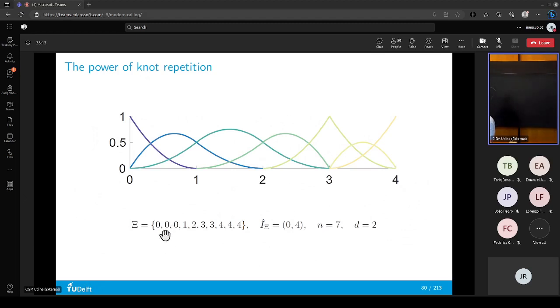It is open because at the beginning and at the end we are repeating 3 times. And in the middle we repeat it 1 time, and you see what it does. So these quadratic basis functions are very nice and smooth, C1 smooth. Here at the third point, we reduce the C1 to a C0 continuity. So that allows us to represent a kink.